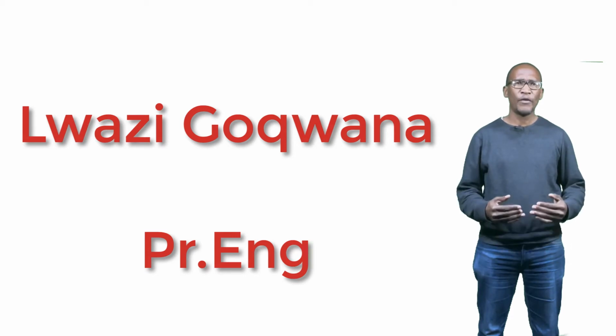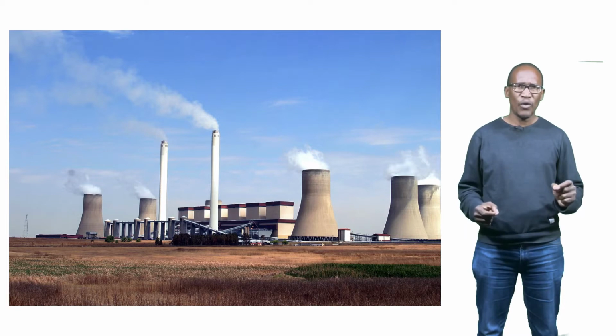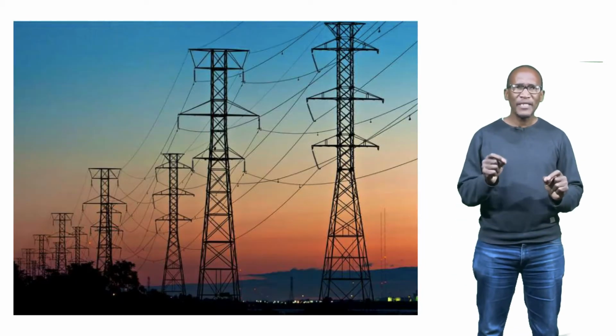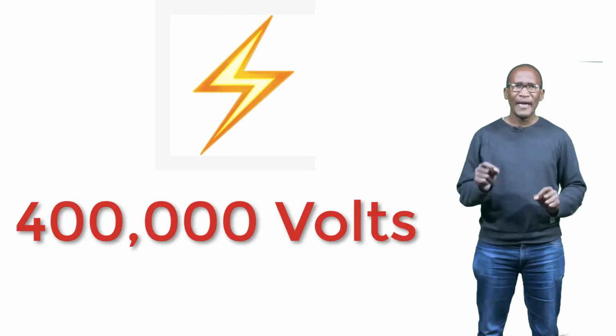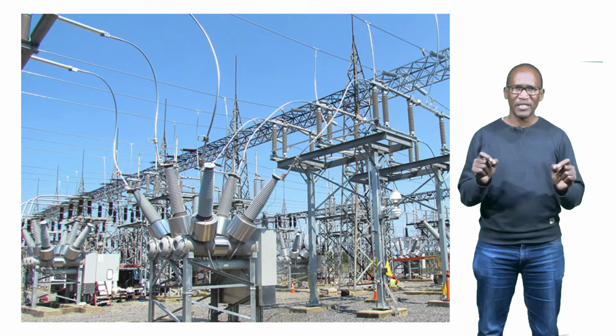Electricity is generated from coal-fired power stations, typically in Mpumalanga, where there is an abundance of coal, and more recently from renewable power plants, mostly in the Northern and Eastern Cape, where there is an abundance of sun and wind. It is then transmitted to users across the country via a long network of transmission power lines at about 400,000 volts. Electricity is then stepped down as it reaches the municipalities, towns and substations to about 11,000 volts and